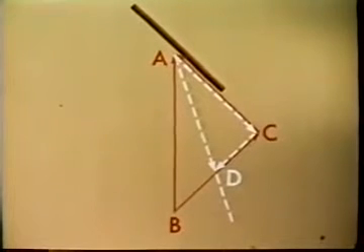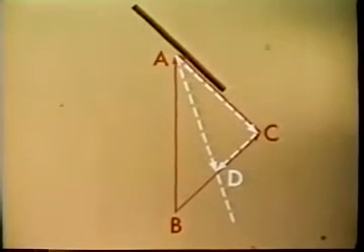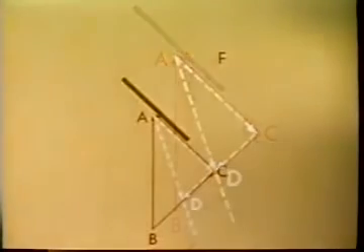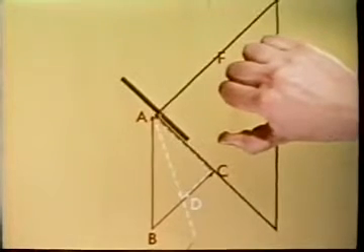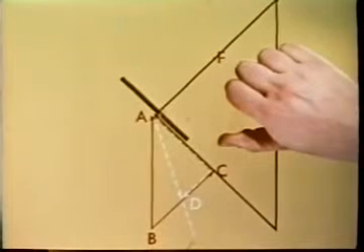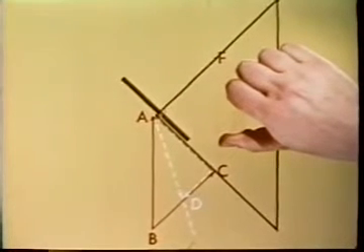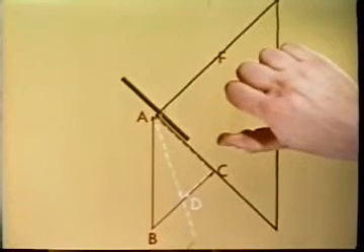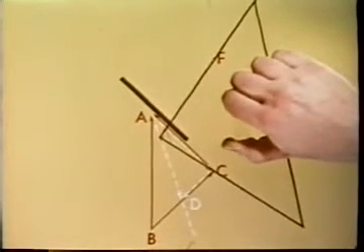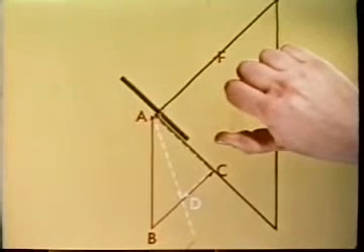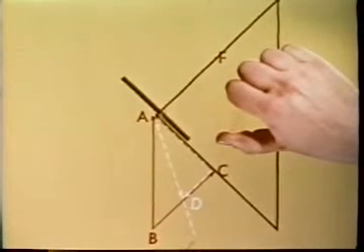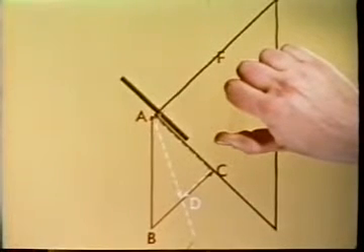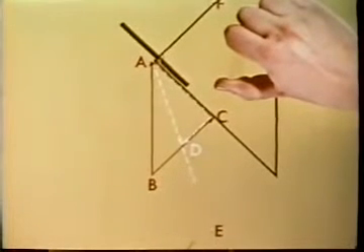To find the largest possible angle of the flight path to the vertical, this geometrical construction can be materialized using a draftsman's square and two drawing pins. The pins are placed at C and a point F situated vertically above C at a distance equal to AB. This square can be moved round so that its two perpendicular edges are in contact with the pins. The axis of the cylindrical falling body coincides with the lower edge of the square. The flight path is then the line joining the corner of the square with the point E, situated vertically below C at a distance equal to CF.